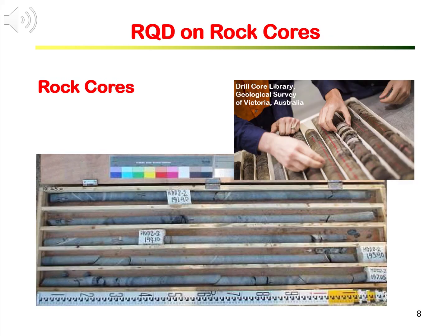It is a common and basic practice that after obtaining cores from site investigation drilling, we do core logging. Core logging includes descriptions of rock and rock joints, including rock types, weathering condition, joint condition, joint orientation, joint surface roughness, and other geological and geotechnical features.